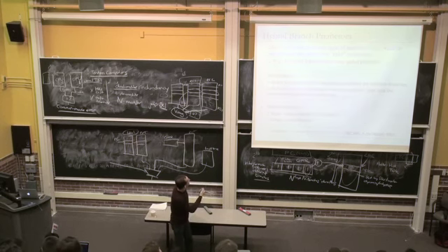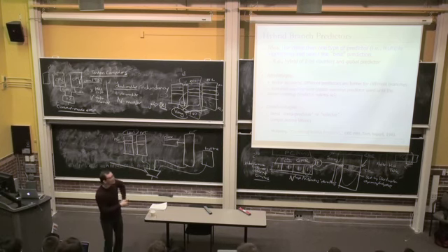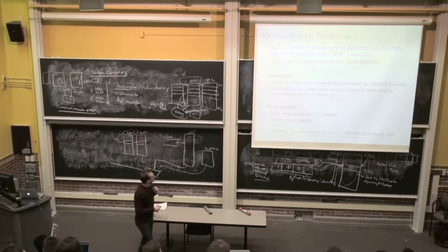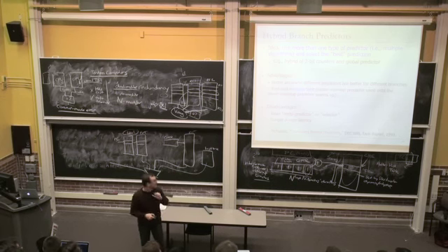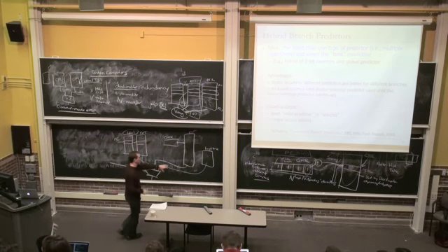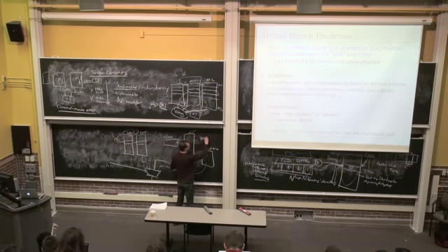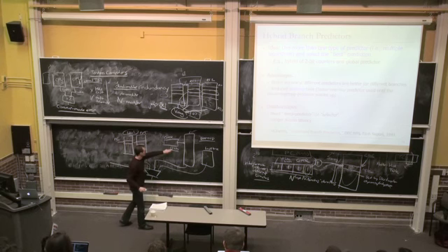Okay. So what is the advantage of a hybrid branch predictor? Essentially, you get better accuracy. You can use different predictors for different branches if you can learn which branch does better with which predictor. You also reduce the warm-up time, if you will. This is what I mentioned here. You can have a faster predictor that warms up faster, and while that predictor is doing well, you use predictions from it. Because here, warm-up means whether the predictions are actually warmed up. Here, you don't need that much history. If your history is 12 bits, you have to see that branch at least 12 times for the local history. Make sense?